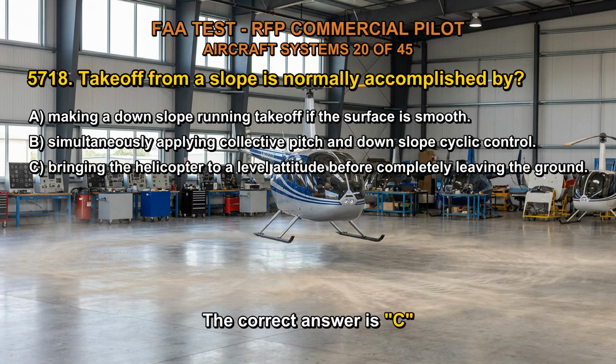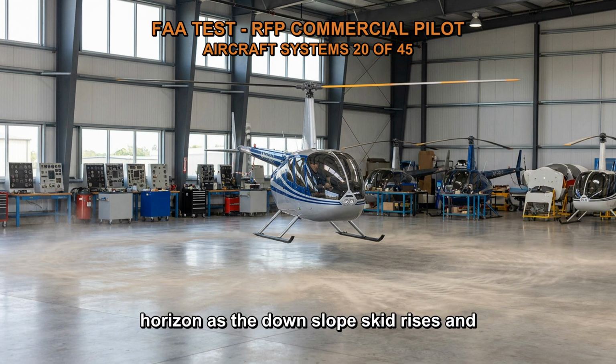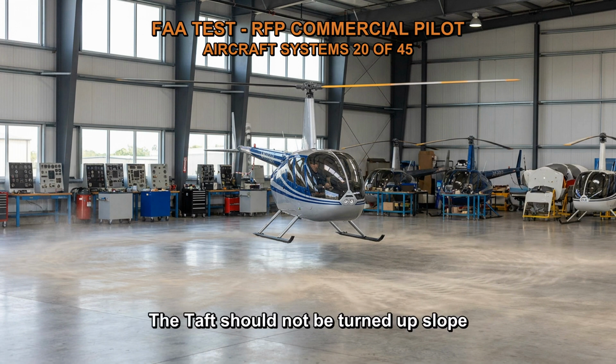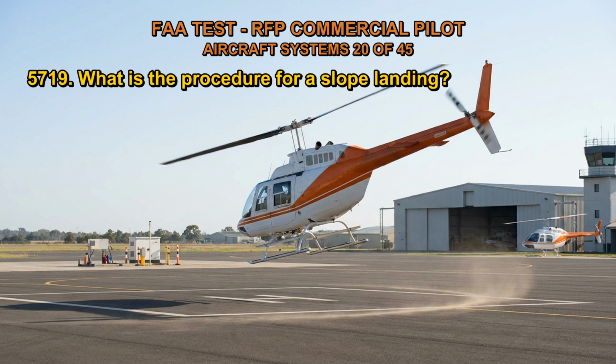The correct answer is C. Move the cyclic stick back to neutral while keeping the rotor disc parallel to the true horizon as the downslope skid rises and the helicopter approaches a level attitude. Apply collective pitch as you move the helicopter away from the slope, bringing it straight up to a hover. The tail should not be turned upslope when traveling away from the slope, due to the possibility of the tail rotor contacting the surface.